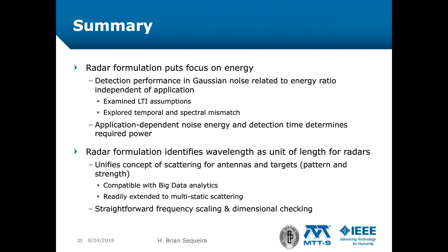Another aspect of our radar formulation is to identify wavelength as a natural unit of length for all radars and therefore express all quantities in terms of wavelength. This unifies the concept of scattering for antennas and for targets and reinforces the intimate relationship of target dimensions and wavelength and its scattering properties.